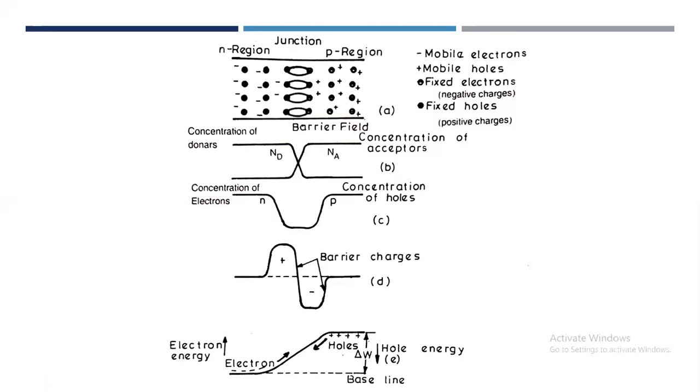The exact nature of the transition from donor to acceptor differs between the growth junction and the fused junction, being much more abrupt in the case of fused junctions. However, the essential behavior is much the same in both cases, in the growth junction as well as in the fused junction.